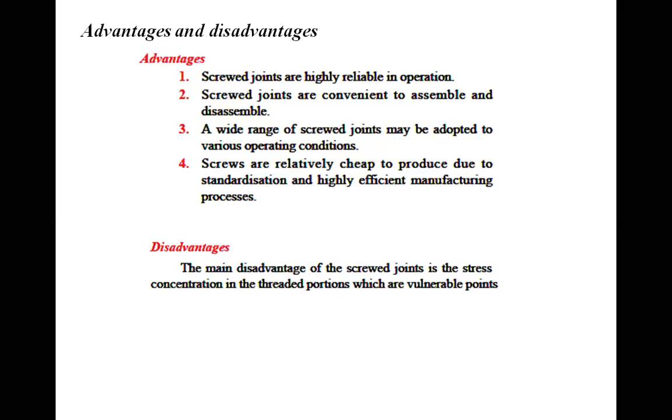In addition to that, screw joints are not that helpful if there are heavy shocks and heavy impact loads, as they may get loosened. That is why we need one more locking nut and other things. Okay.